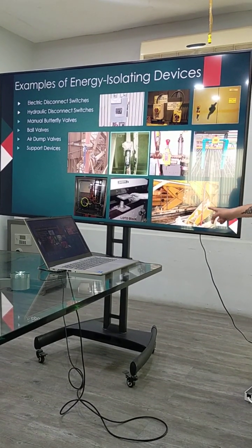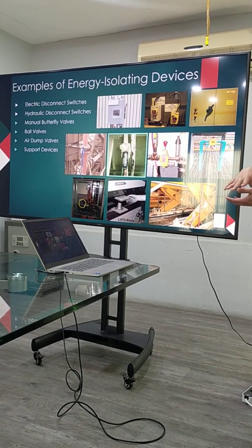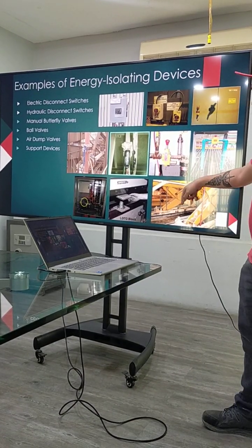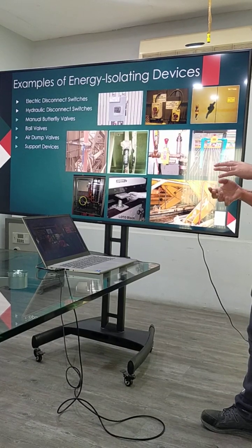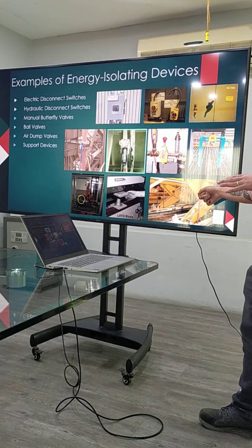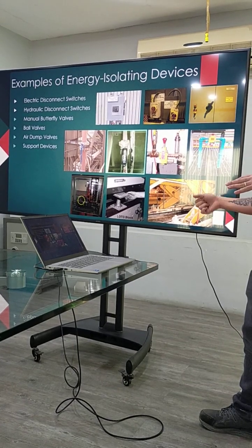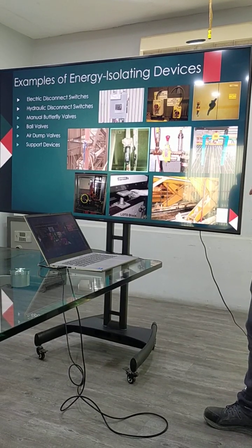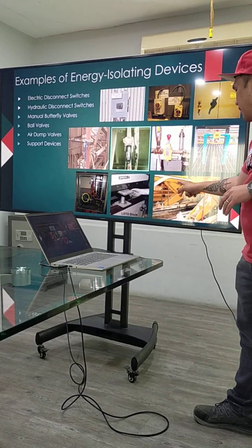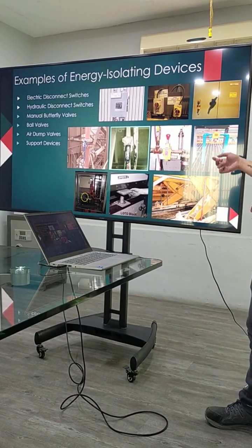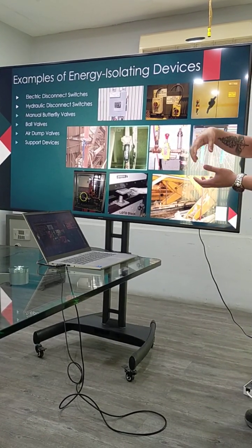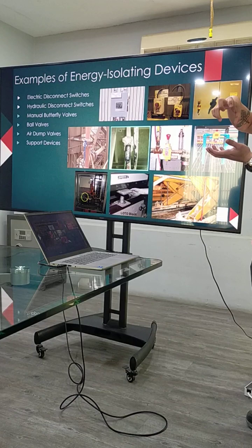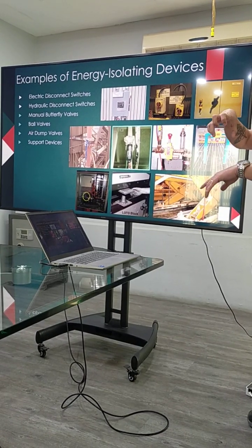As you can see, these support devices are for the lifting table. I think we do not have this one. Once you enter inside, there is a mechanical part driven by the hydraulic. What if the hydraulic fails? The tendency is that it will go down. But if you have support devices, it's better. Other support devices we can provide, because in our plant we have footing, sling, and a cam lock to ensure that the table will not go down when someone is working inside.